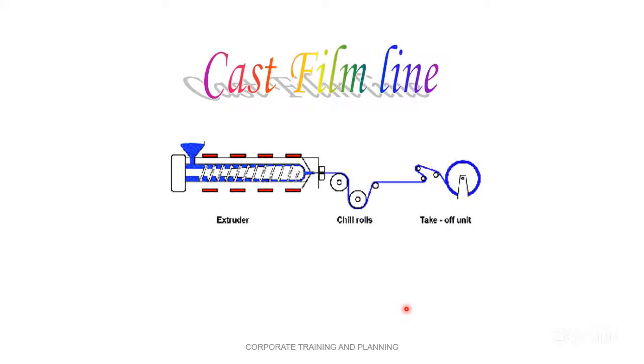Now here, cast film line. I am taking the majority, extrusion frame, because you should know what the blown film is and what the cast film is, because film is also manufactured by casting, right? How are blown film and cast film differentiated? Now see here, the same extrusion is there, friend. There is a chill roll here, right? It is a very cold roll, the temperature may be 4 degrees here, and these are the guiding rolls, right?